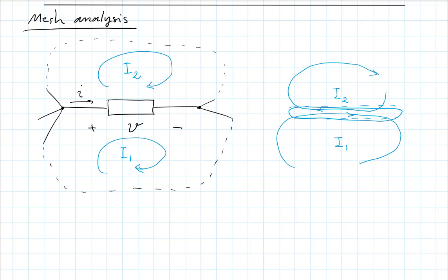So this is an abstract concept, or a tool, so that you can represent the element current in terms of these mesh currents. And you can see in a very simple way that once you do this and you draw a circuit that has a bunch of meshes connected, your KCLs will be automatically taken care of, because you have all these mesh currents going in meshes that surround each node.